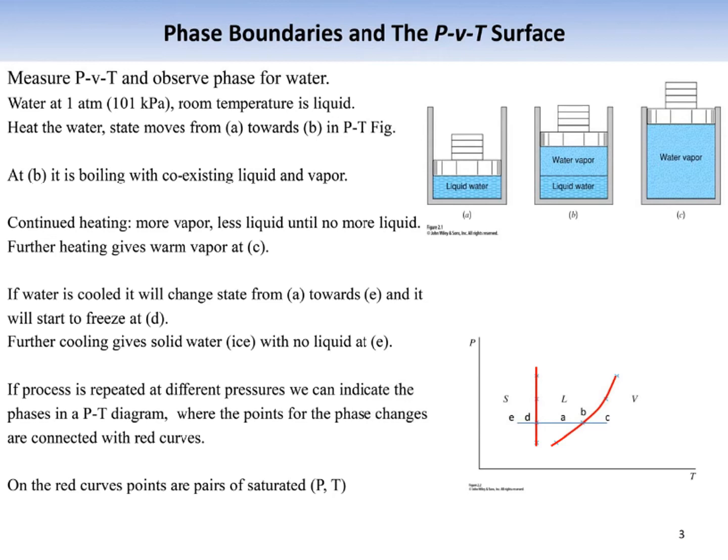Whenever we increase this weight, there is a change in internal pressure because of the external forces. However, if the external weights remain constant, then internal pressure remains constant, because the piston will move up and down to compensate, and this motion continues until the internal pressure becomes equal to the external pressure.